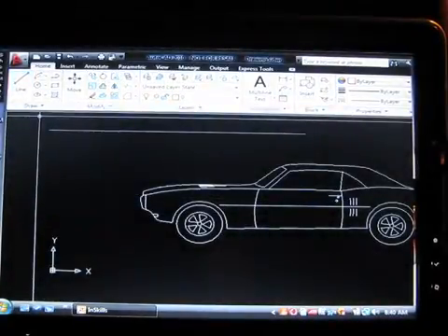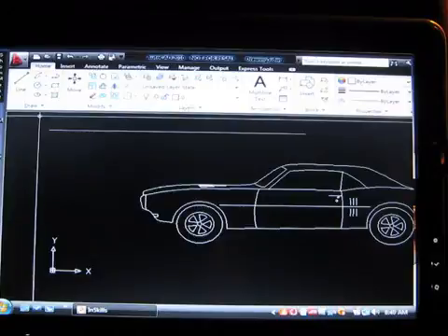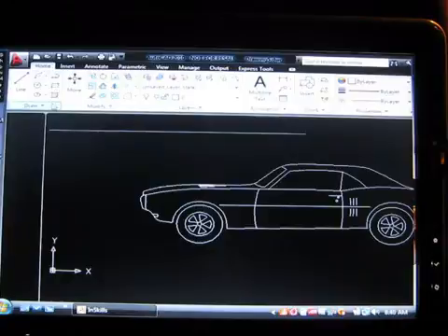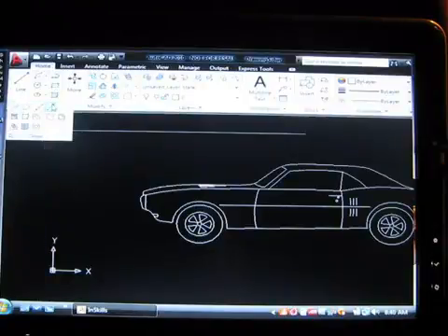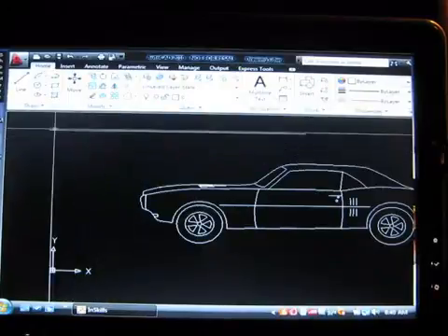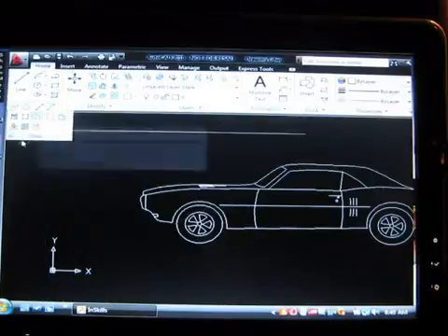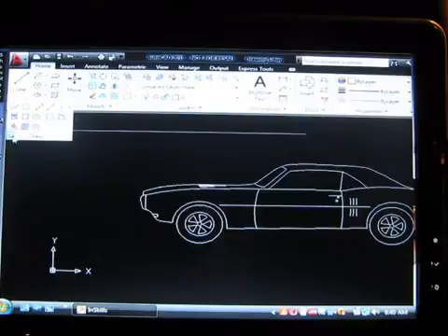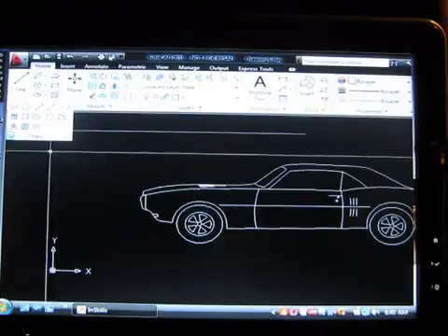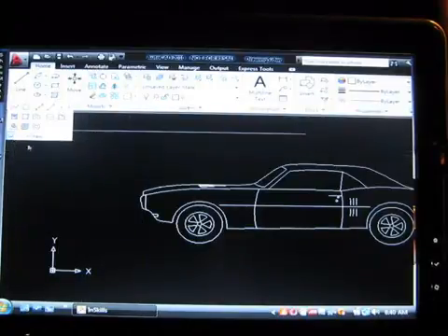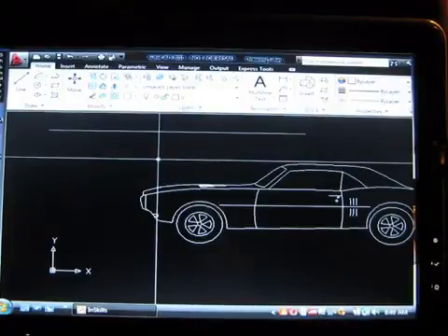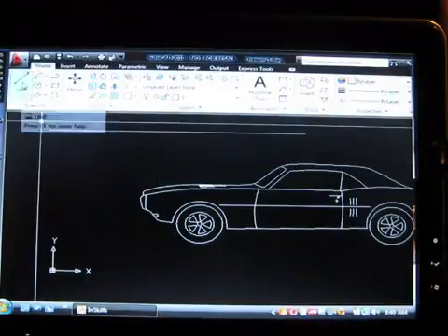Some of the panels collapse, meaning that they shrink so as to give you more room on your screen. There's an icon in each panel that indicates this feature. Just hover over it and click it to expand the panel. When you're done, move your mouse away, it will go back. If you want it to stay, click on the pin icon to pin it in place. If you don't want it pinned anymore, click it once again and move away. To activate a command, simply click on the command icon like this.